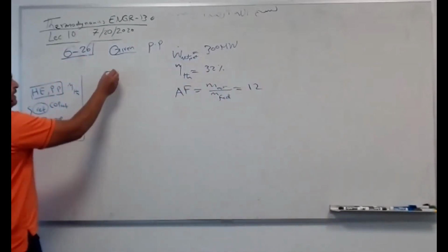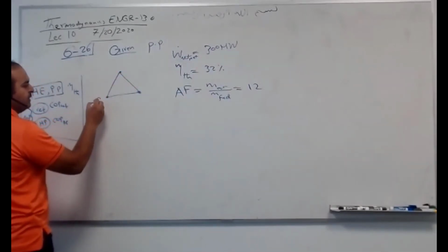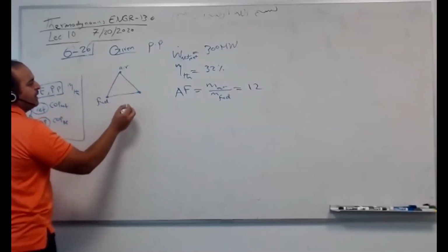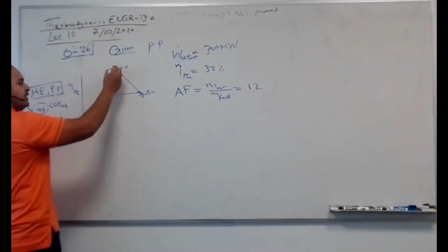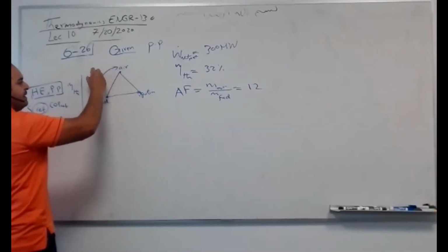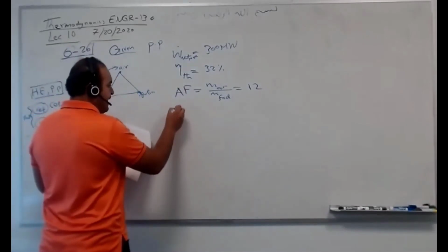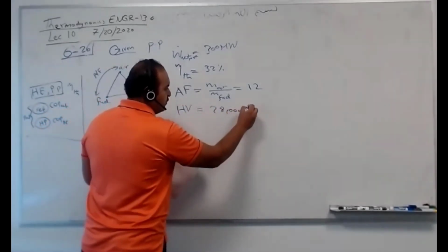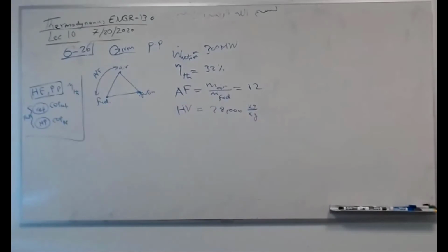As you know, we have 3 things to have successful combustion. We have fuel, we have an oxidizer, like air, and we have the ignition. The air to fuel ratio is something so important in engines. M dot air over m dot fuel is given here. Heating value was 28,000 kilojoule per kilogram. So for every kilogram of this fuel, I can get 28,000 kilojoule.